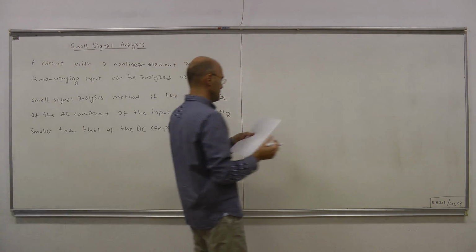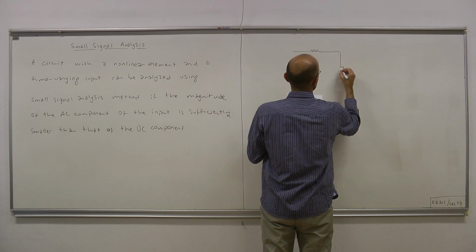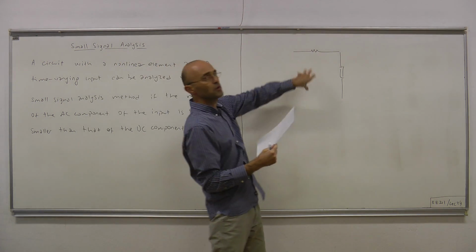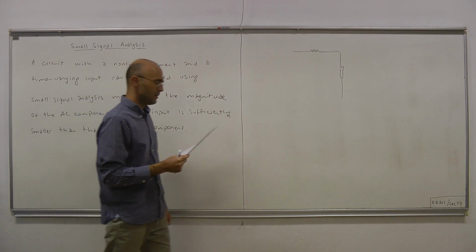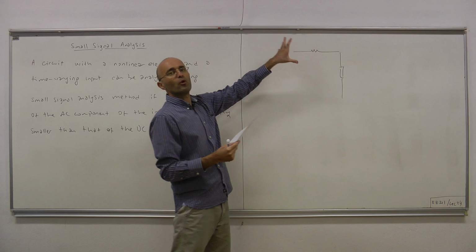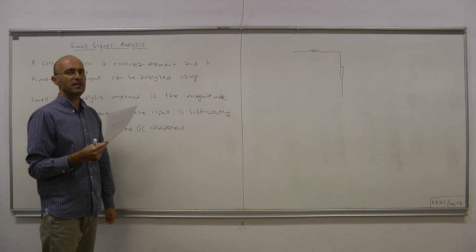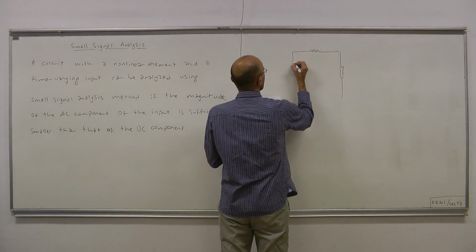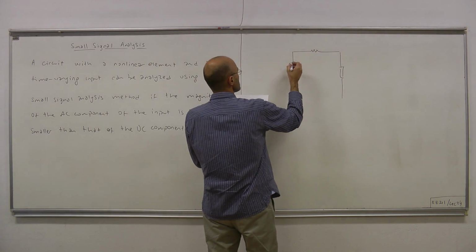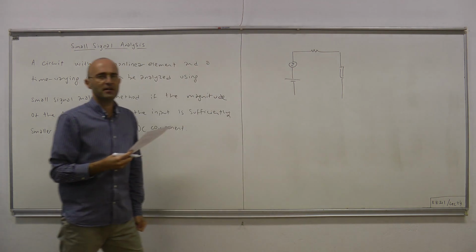Now, what we're talking about is the following circuit. Again, we have a nonlinear component connected to a simple linear one port, or something more complicated but linear. Therefore, it always can be represented by its Thevenin equivalent, which would have the following form: the Thevenin resistor, and an independent voltage source.